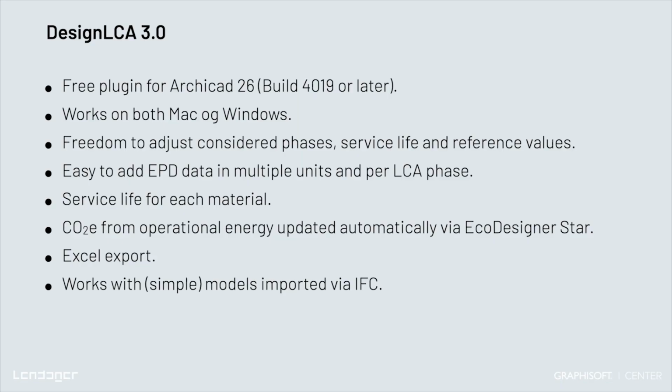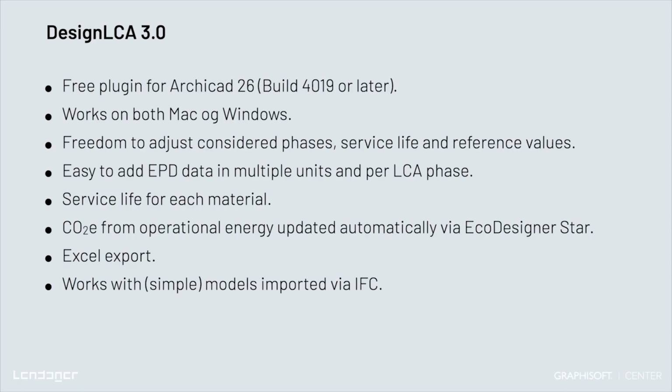so please read the manuals. So just to sum up, Design LCA is a free plugin for Archicad 26. It only works with build 4019 or later, and that's because that's where you get the free EcoDesigner Star if you are on a service agreement or Graphics Forward. It works on Mac and Windows, and you can choose what phases you want to include, how long lifespan you want to include, and you can put in your own reference values.